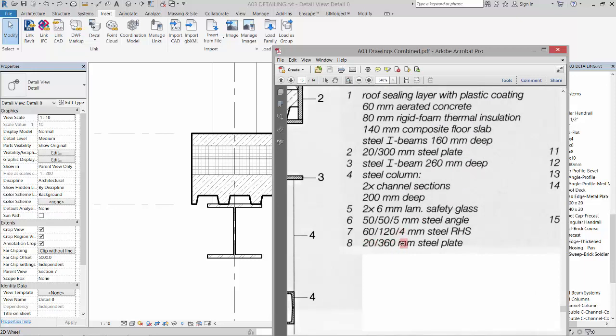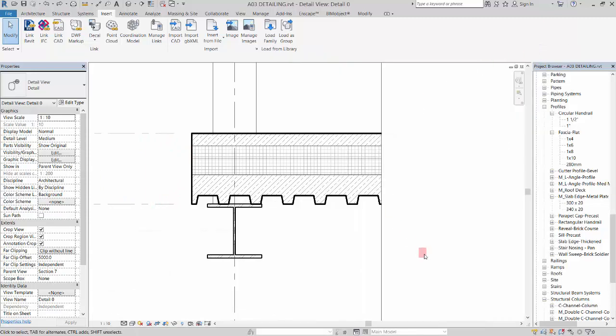And I've given you guys a profile family. We're actually going to create a model piece that is this plate, because when we have this in a 3D view, it would be nice to have that plate all the way around this edge. So I gave you a profile family, which we've worked on profiles before, that's going to create this sort of slab edge for this floor.